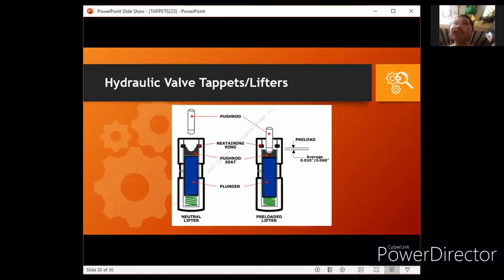But if set too high, the spring may be damaged and slams up and down instead of the squeaking noise of a plunger. So a preload must be set once installed to prevent those two occurrences.